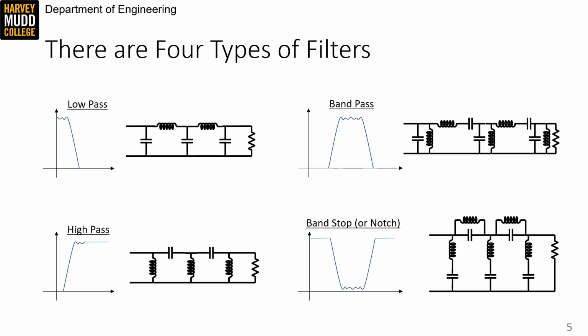The picture we've been looking at thus far was a bandpass filter, but the filter prototype can be used to describe all 4 types of common filters, which, as a reminder, are low pass, high pass, bandpass, and bandstop. You can build lossless LC ladder versions of each of these filters, and I've drawn them on this slide. Thinking about the asymptotic impedance of each component can give you some intuition about how the low-pass and high-pass filters I've drawn exhibit the low-pass and high-pass behavior.